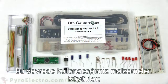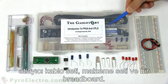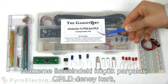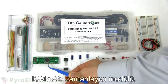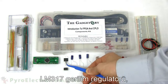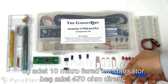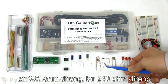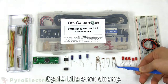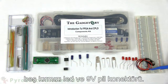Here are all the parts that we'll be using in this experiment. The larger parts are a jumper wire kit, components kit, and a breadboard. The smaller parts from the components kit are a CPLD breakout board, an ICM 7555 timer module, LM317 voltage regulator, 3 10 microfarad capacitors, 5 470 ohm resistors, a 390 ohm resistor, a 240 ohm resistor, 3 10 kilo ohm resistors, 5 red LEDs, and a 9 volt battery connector.